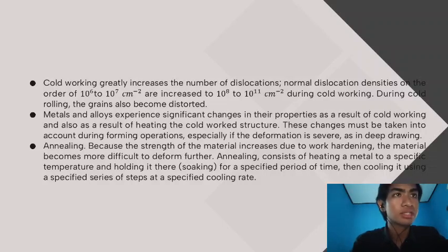Accordingly, isothermal recrystallization curves are typically sigmoidal in shape because there is an incubation period during which no visible recrystallization occurs. During incubation, there is an irreversible coalescence of some grains, which grow until there is enough energy for them to attract enough atoms and become a stable nucleus for the onset of crystallization.